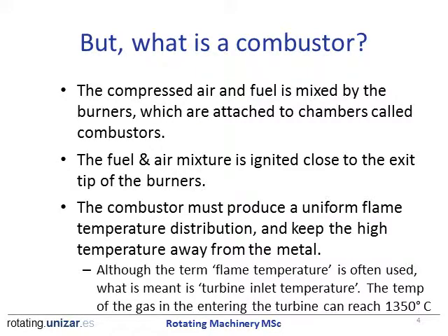And the function of the combustor, as we said, is to produce a uniform flame temperature distribution and also keep the high temperature away from the metal. One thing that is important to mention, because even in these modules we'll discuss a lot about flame temperature, is that flame temperature is not realistic, it's difficult to measure, and also is not useful.